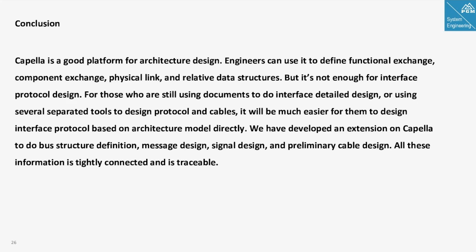For those who are still using documents to do interface detailed design, or using several separated tools to design protocol and cables, it will be much easier for them to design interface protocol based on the architecture model directly. We have developed this extension on Capella to help us do bus structure definition, message design, signal design, and preliminary cable design. And all this information is tightly connected and is traceable to each other.